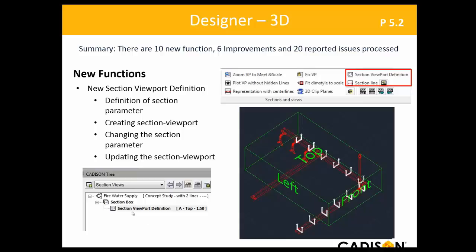And what we can do later is we can take this section view and we can make it by drag and drop and move it on our layout, so that we get our 3D to 2D in a very fast way, and we can make all modifications also here in the database objects. We must not go back into drawing. Very smart, and I think that is one of the biggest improvements. It also took a long time to get this to happen.